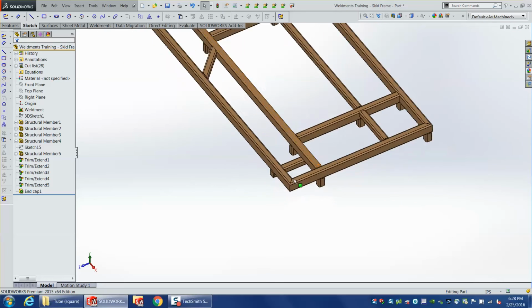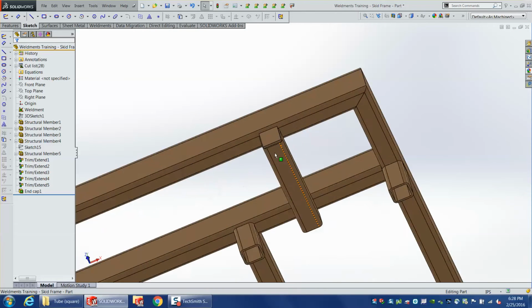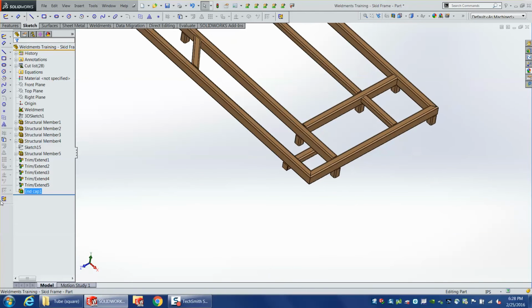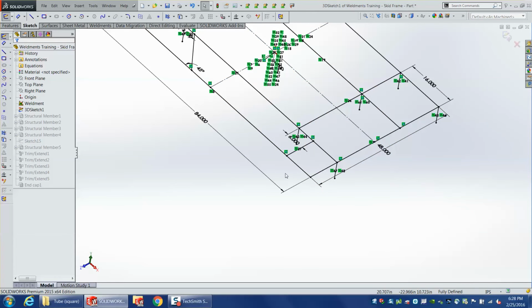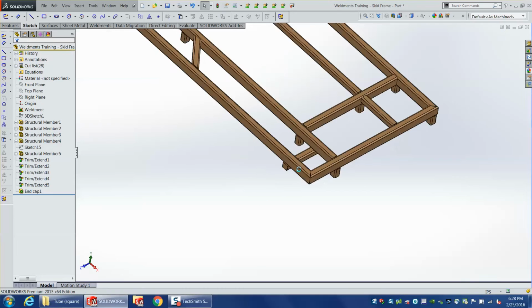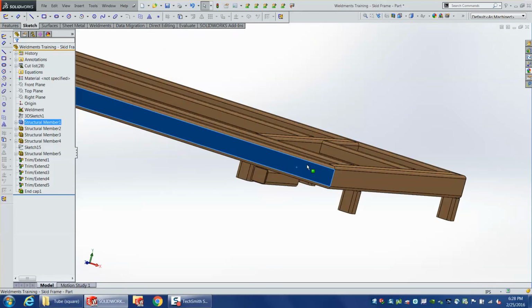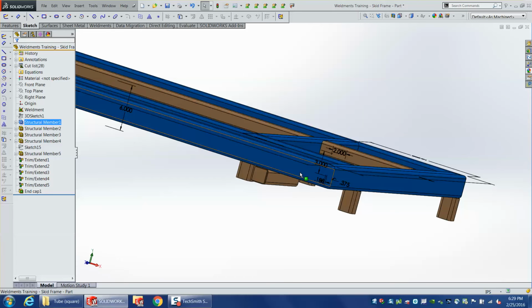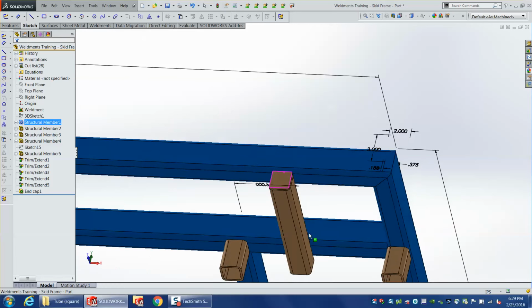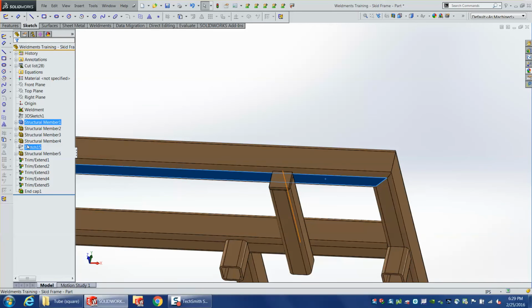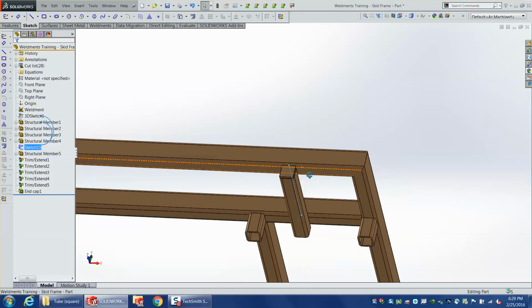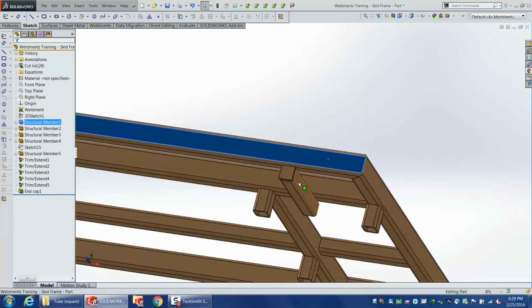Also on that feature, I stuck it underneath, and I could have done this with a 3D sketch by drawing a construction line down here and putting a number and having a line going across. The reason I didn't do that is if I change the height of this tube, that number would be wrong. And so this is actually stuck to the lower face. It's a sketch on that face, so that if I change this to a 4x2, that tube just moves down with it.